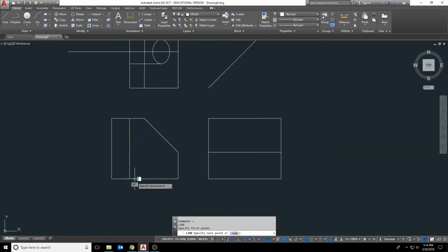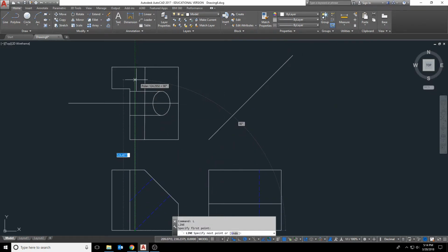This is actually going to be a curvature that we're going to see on the bottom of this shape, so I need to put in another ellipse between here, here, and here, and what we're going to be seeing there is where the bottom of this shape cuts out the actual object. So we'll go ahead and trim this, and this now gives us our hidden lines.